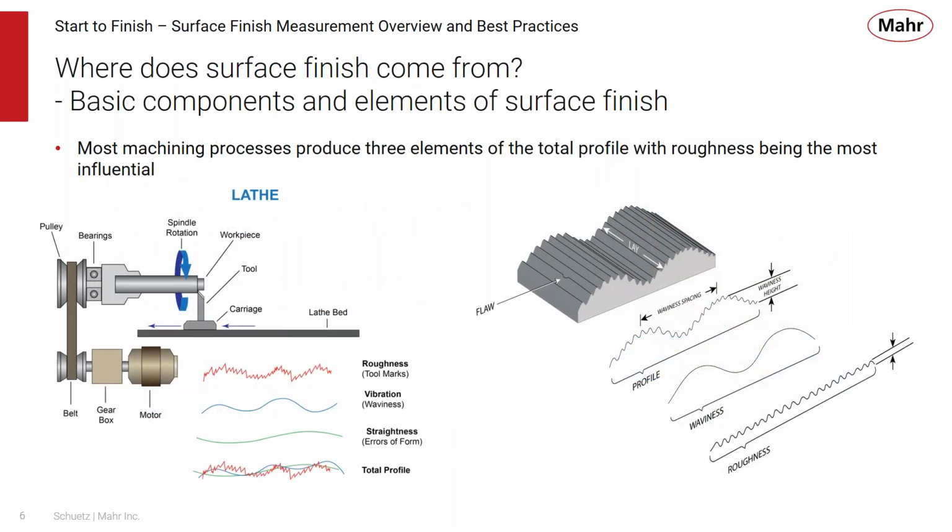So where does the surface finish come from? We talk about the machining process, and here's a typical lathe, and the parts of that lathe are going to really put a fingerprint of that manufacturing process onto the parts. Those parts of the process are the cutting tool itself, and the ways and the lathe bed, for example, which have some straightness errors in them. You might be getting some vibration from the motor or the gearbox.